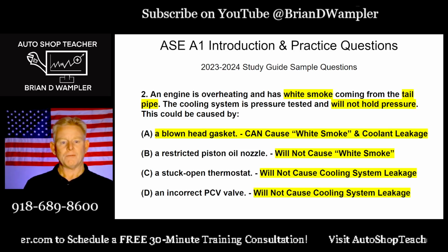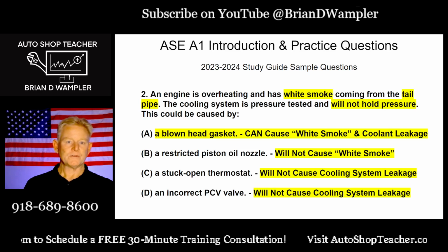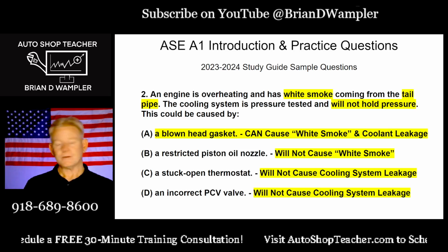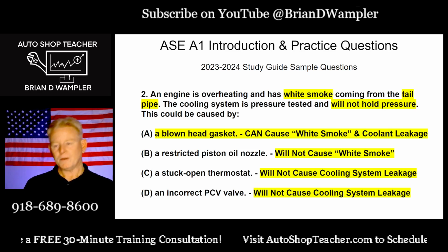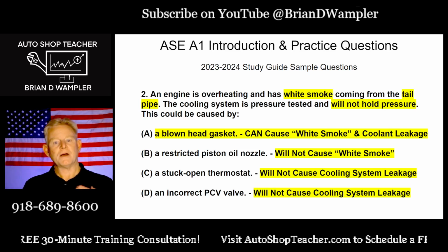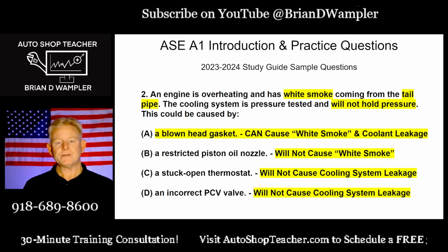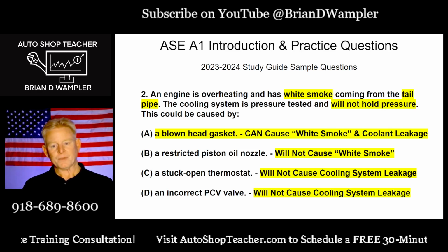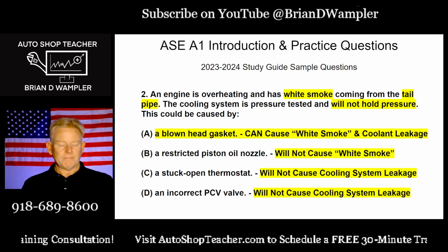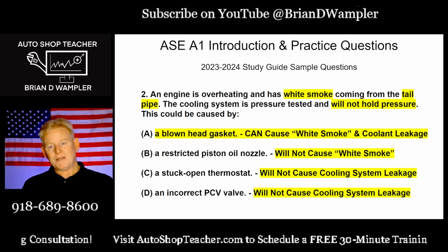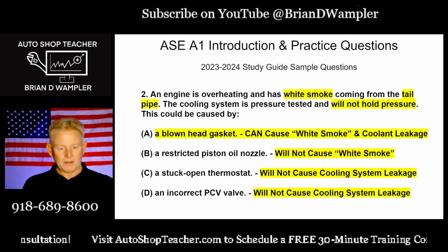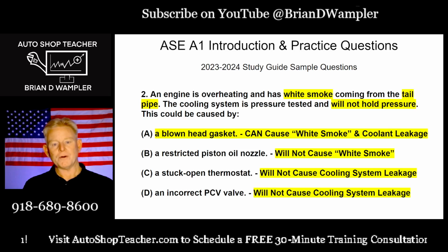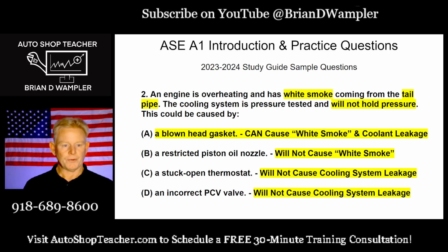Not talking about oil that's gotten onto the exhaust, but if you've ever seen that, the smoke off of something like a leaking valve cover is kind of bluish. But we're talking about a large quantity of blue smoke out the tailpipe. That's usually associated with oil that's been through combustion. Okay, so not from other sources, but actually been into combustion, meaning into the air-fuel mixture, compressed, ignited, the oil burns, and it typically leaves a blue smoke.